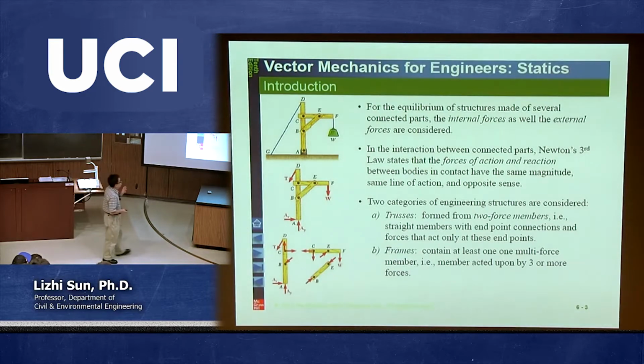In chapter 4, we talked about the reactions. Reactions are external forces acting on the rigid body, because with the reaction we can support such a rigid body with applied load or applied moment, and then we can calculate what the reaction or resistance is, so that we know how much the support needs to provide. On the other hand, even inside the rigid body, specifically for this problem we call the truss, we also need to know how to calculate the internal force.